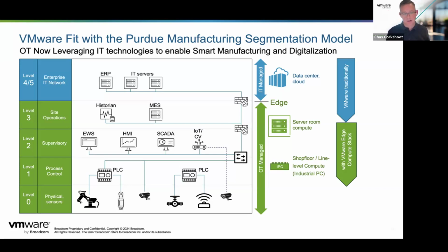So today our goal is, a lot of those PLCs do monitoring, for instance. They're not mission critical. They're not in the paint shop, for example. It's kind of an 80-20, 90-10 rule. The 10% is the high criticality, where they need two physical pairs with millisecond switch off. So we can start to virtualize those PLCs and bring them together, and start to take on more controls and deal with things like PTP protocols and security lower down the stack. So that's the journey we're on.